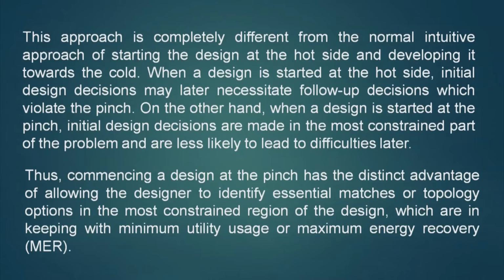Thus, commencing a design at the pinch has the distinct advantage of allowing the designer to identify essential matches or topology options in the most constrained region of the design, which are in keeping with minimum utility usage and maximum energy recovery.